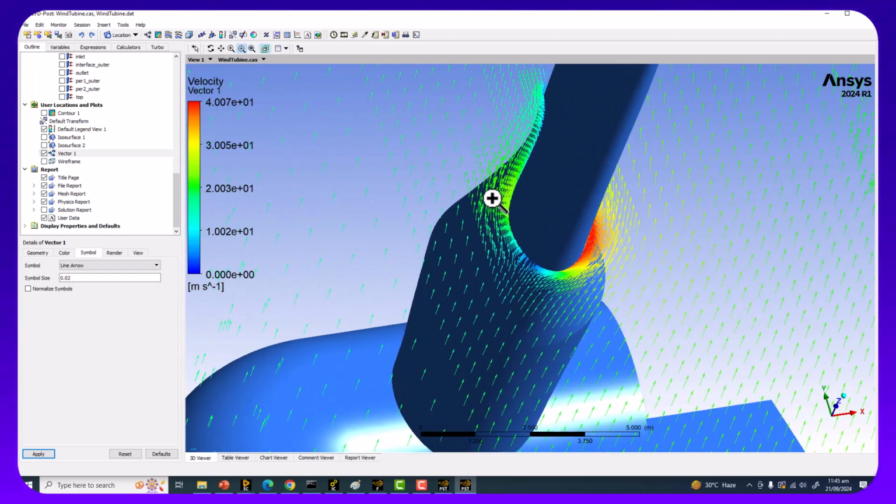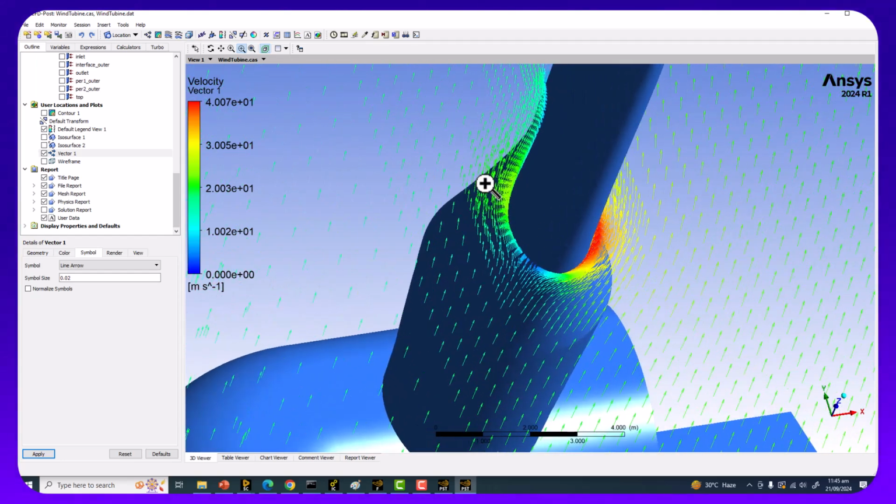Can you see one thing: in Fluent this was showing the wrong values. It was not showing the relative velocity vectors. I didn't tell you at that time because I didn't want to confuse you. At that time, even though I was showing the absolute velocity and the relative velocity, they were showing the same, and it was actually the absolute velocity.